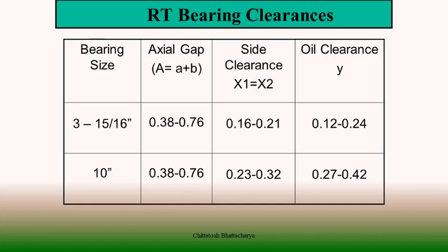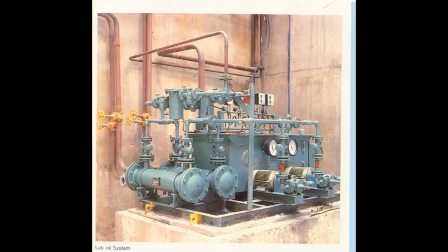And in case of oil ring lubricated bearings, the lubrication may be through an assisted lubrication arrangement with pumps, or there may be supply of oil by ring lubrication. Anyway, in most systems nowadays we have oil pumps and continuous supply of lubricating oil, and there are lube oil pumping stations fitted with strainers and coolers, so that lubricating oil can be continuously recirculated back, cleaned and cooled, and again supplied to the journal bearings. So this way we arrange the bearings and their lubrication.